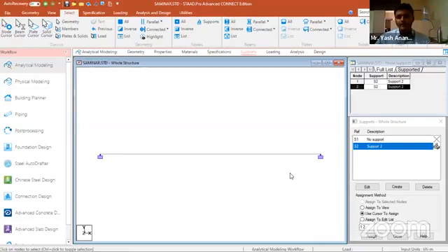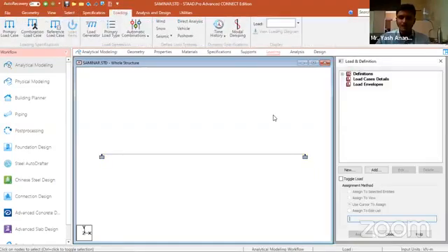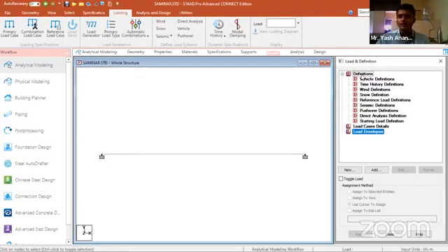Our geometry is now done, and all we had in the problem is specified. Remaining is our loading condition, which type of load is acting on a particular beam. For that, we apply load on this beam. So here I am going to the load tab. After support, there is a load tab. In the load tab, you can see there is a load envelope, definition, and load detail, and here we are going with definition.